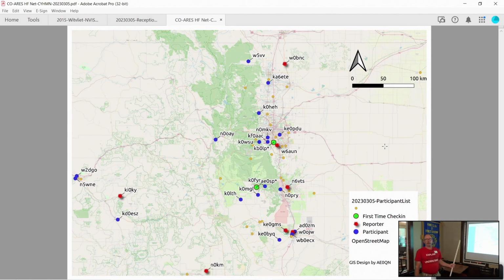Well, when you look at some of the resources, some of the links I posted, you'll find out that when you come down from that quarter wave height down to like 1/10 of a wavelength or even a little less, down to about 15 feet, you really don't lose a lot of transmit signal on NVIS. You're not hurting yourself a lot yet. And on receive, you're actually doing better because you're not hearing as much noise off the sides.